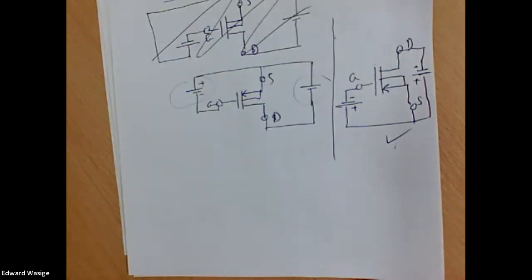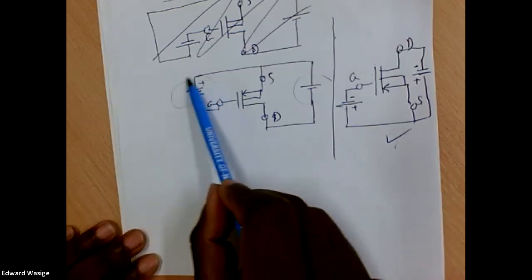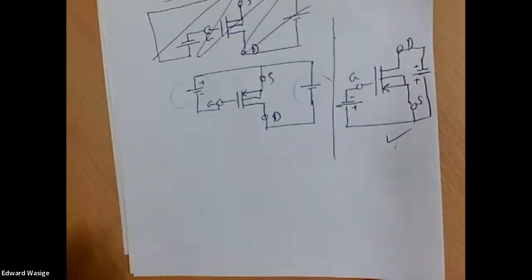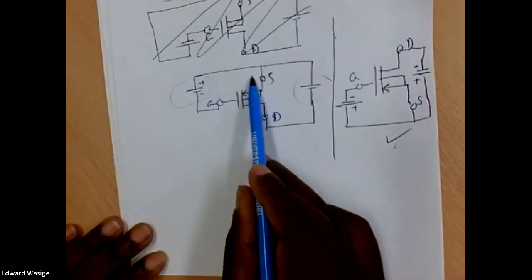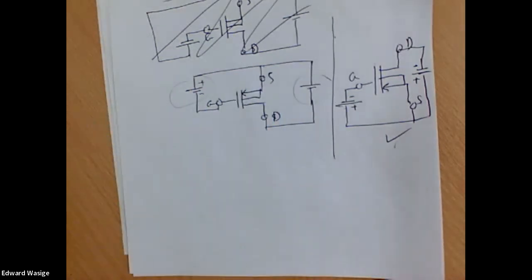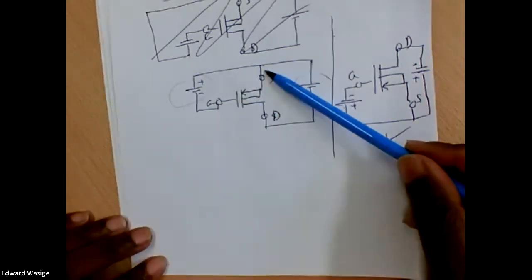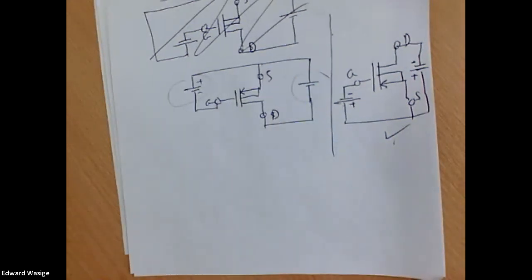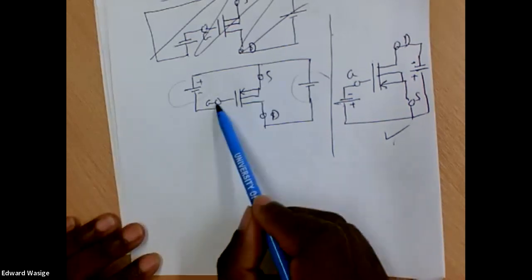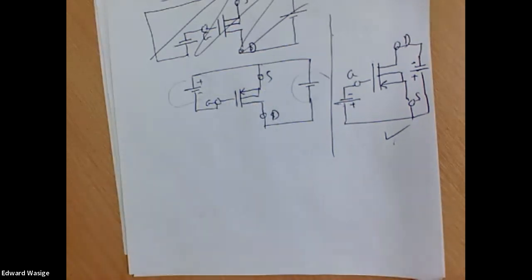That's quite important when you draw your circuitry, because even though you only have one positive supply, it can supply your NMOS in the normal configuration, but the PMOS device will normally be flipped the other way around so that the source electrode is in the opposite position compared to the drain electrode. But that way, we have the correct potential to turn the transistor on.